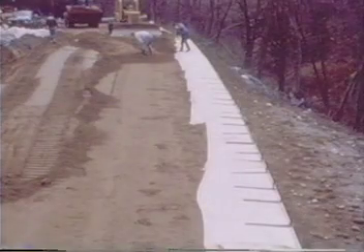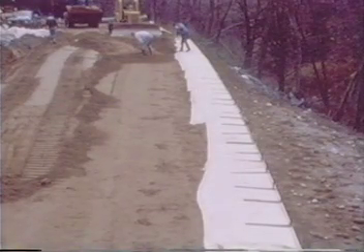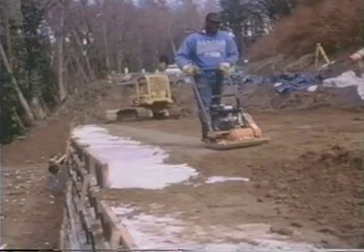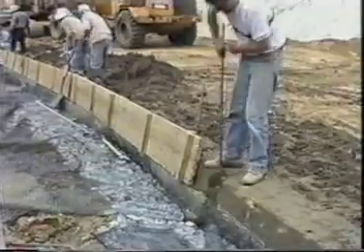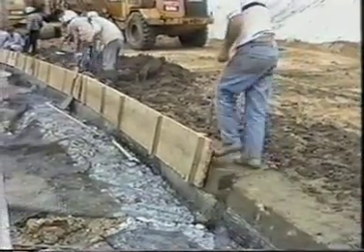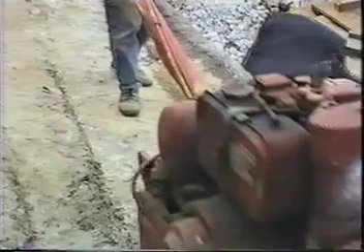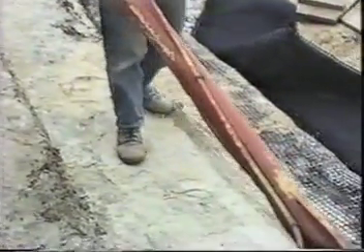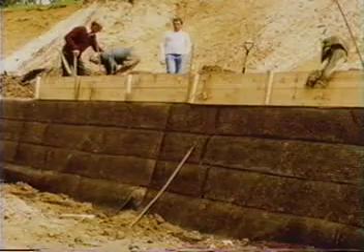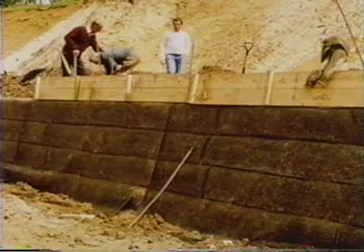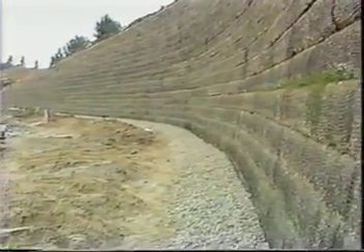As this process is repeated, each layer of fill bears on the previous layer of reinforcement, so preventing the wrapped face from pulling out. The use of hybrid climbing formwork for wrapped faces allows the fill at the face to be compacted to an acceptable level. It also enables construction to high standards of alignment and appearance.